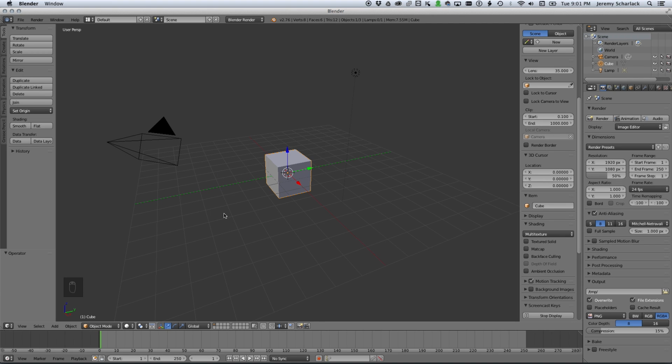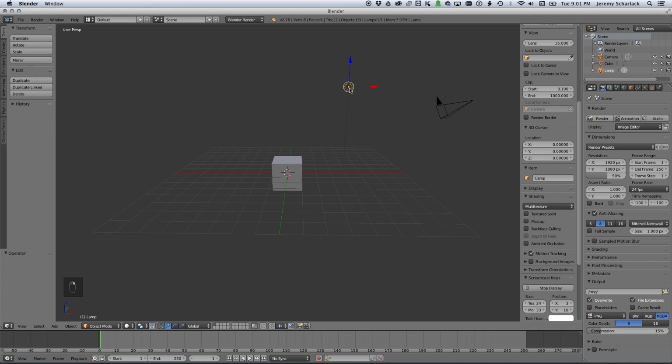You can wander around 3D space by using your middle mouse button, which is usually a scroll wheel. And yes, that means you need a 3-button mouse. Now, if you've got a trackpad or a tablet, it's not actually a big problem. You can emulate a 3-button mouse, but just Google that. Google emulate 3-button mouse. And of course, Blender's one weird feature is that you have to select things by using the right mouse button, not the left. So selecting things is with the right.